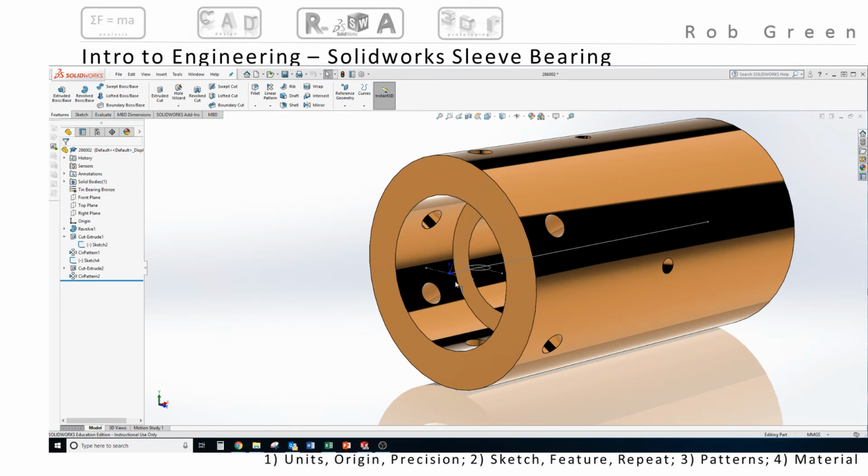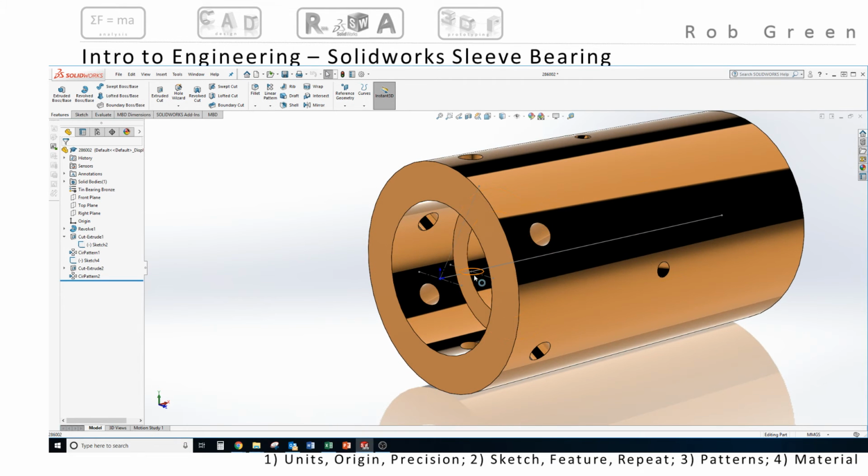If you have been following exactly the workflow that I have done, in your file as well, you're going to be able to see a sketch that we turned on previously. And also this angled line exists in a sketch natively in our project browser. We're not going to want to see those sketch lines in our drawing file because they're not part of the physical part, so let's turn them off.